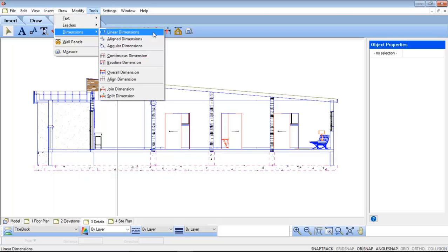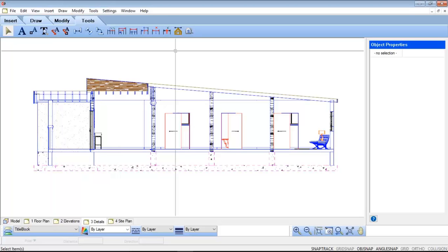So for floor plans, really the ideal is you want to take advantage of those tools in model space before you come and insert into worksheet space. So you don't have access to those tools here, just to bring that to your attention. Everything in here in terms of dimensioning is manual dimensioning tools.